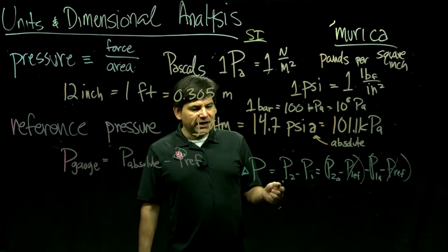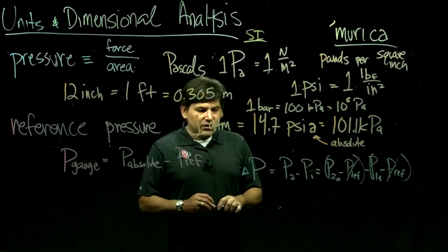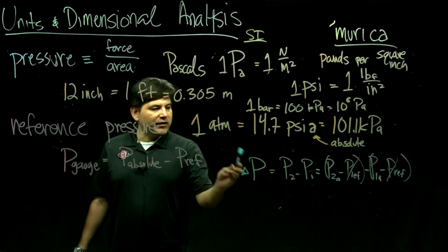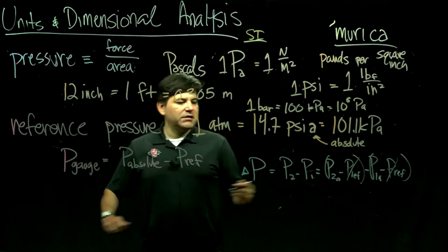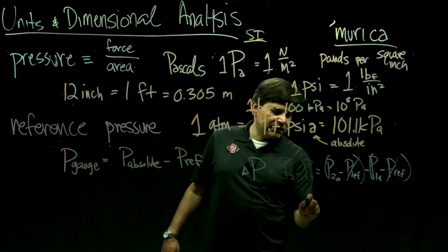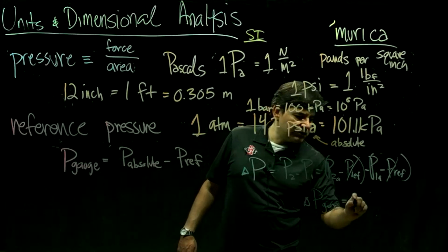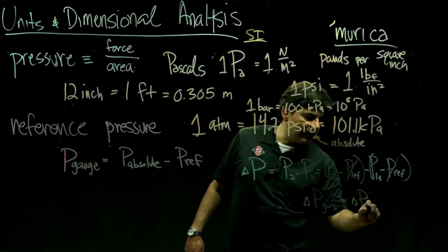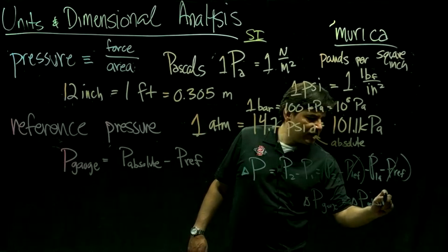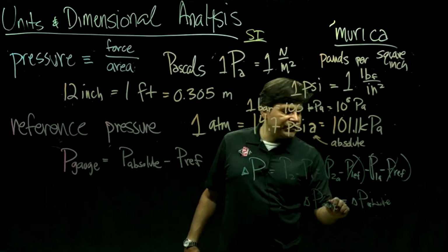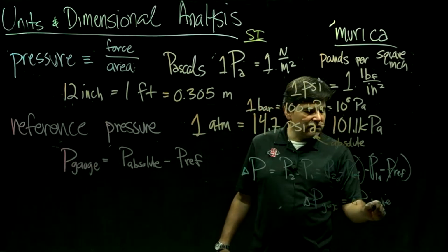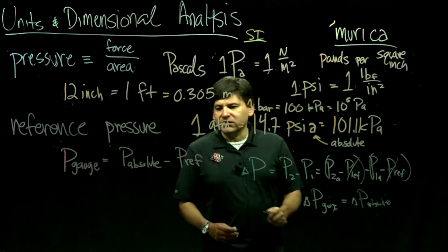So in this example, if you're taking the difference between 2 pressures, it doesn't matter if you're talking in terms of gauge or in terms of absolute, it cancels out. So if you're consistently using gauge or consistently using absolute, the reference cancels out.